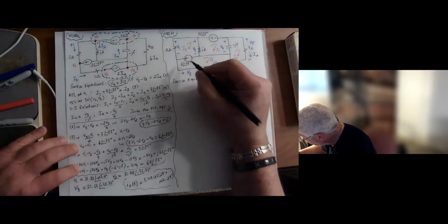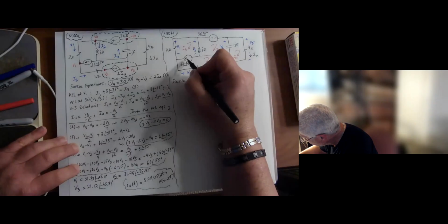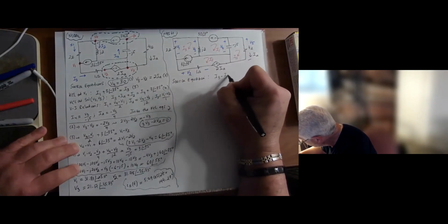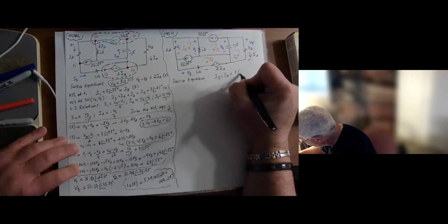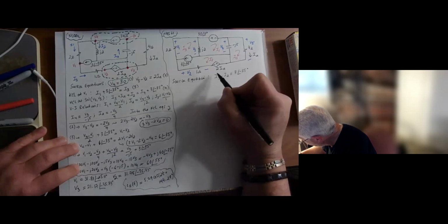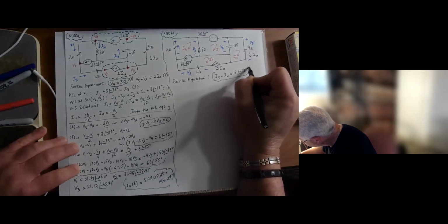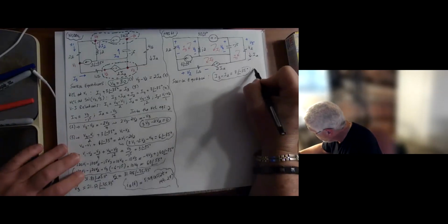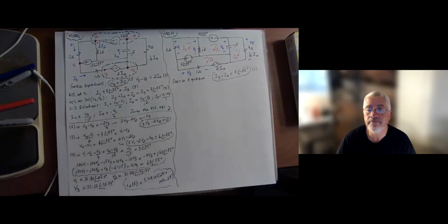In this particular case here, I'm going to write the source equation for this current source. That is I3 minus I2 equal 3 at an angle minus 35. That equation actually is done. It's expressed in terms of the mesh current, so I don't have to do anything. So I can actually box it and call it equation 1. Okay. That's the easiest equation to write.